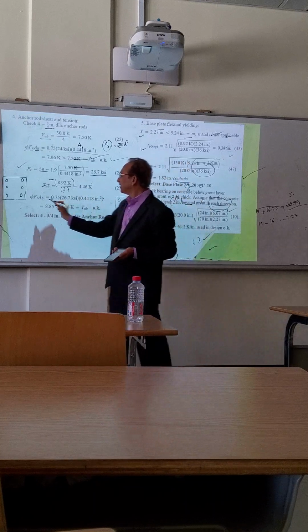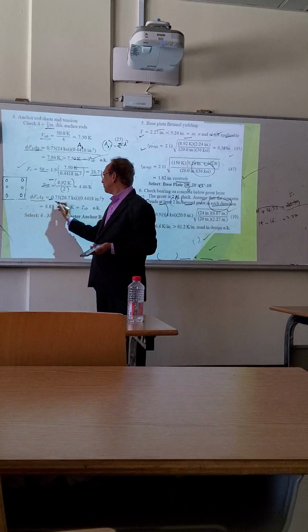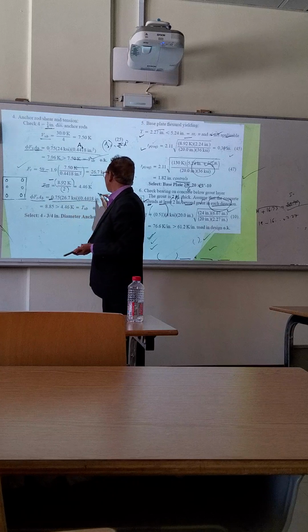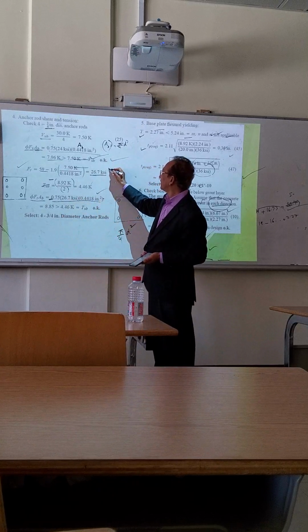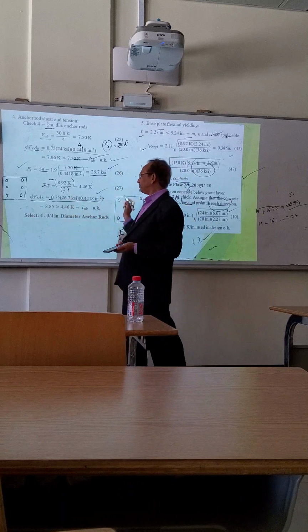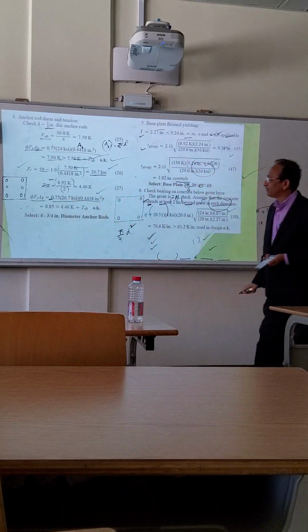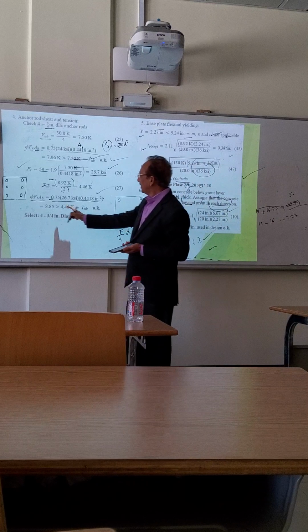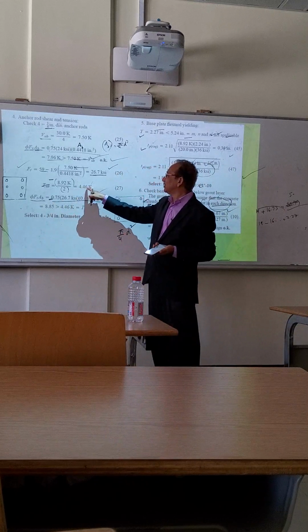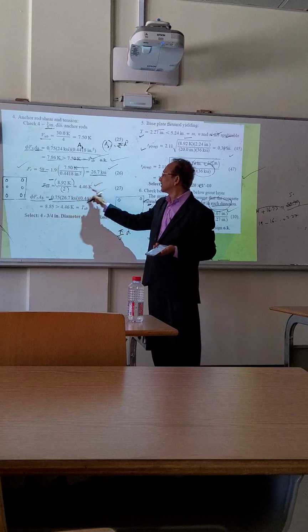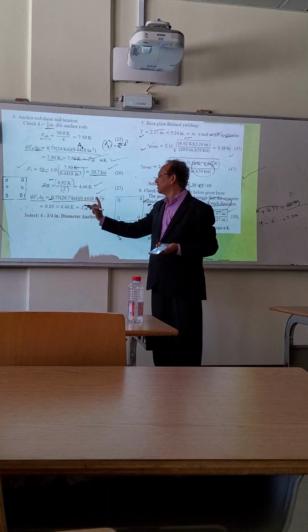Then we calculate here the tensile force Ft, how much? By using that same formula, we substitute here this value which we take from here, and then we confirm that this is 8.85, which is more than the capacity of this, 4.46, and it is safe.